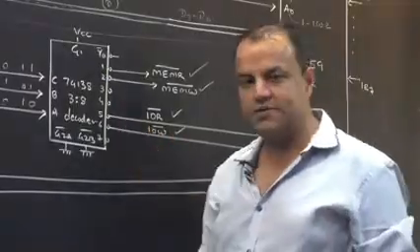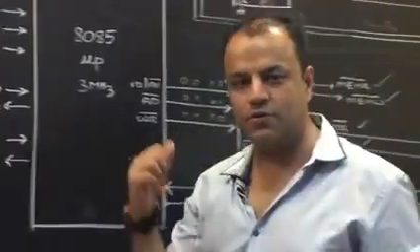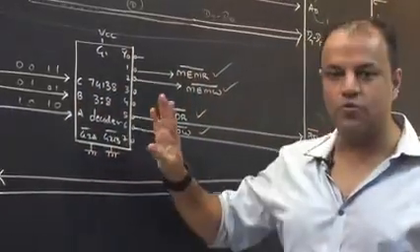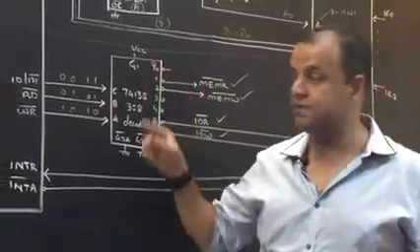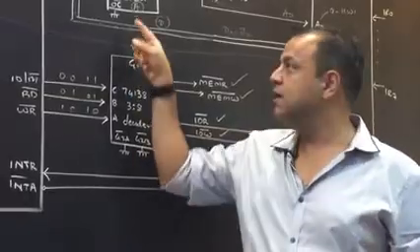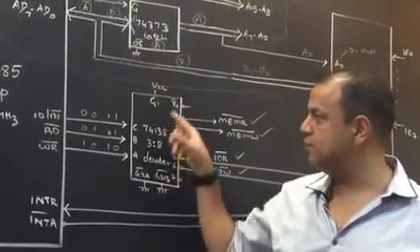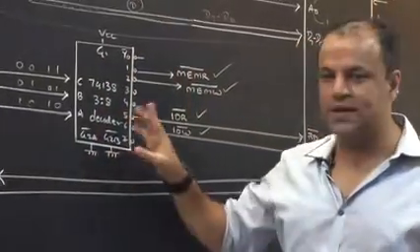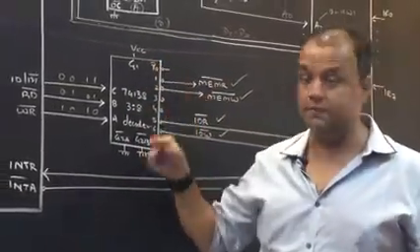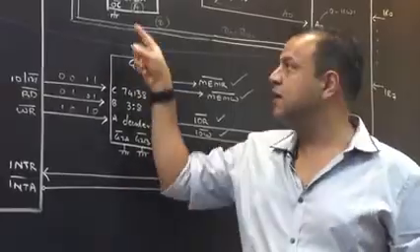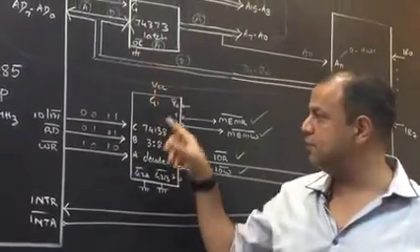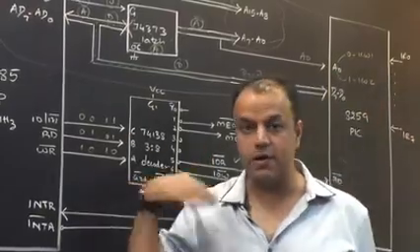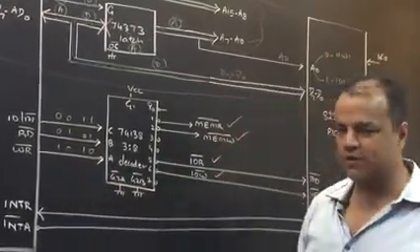You would be saying, why 3 enables? Don't worry. Decoders are not used only over there. Decoders are also used for address decoding. There'll be one more decoder coming in the circuit, and that decoder will produce that final signal that this whole thing is all about. At that time, we'll be using these signals extensively. In this decoder, we don't need them, but we can't just leave them. You still have to enable the decoder, like you enabled this OC bar by connecting it to ground. You still have to show VCC and ground, but they are not really required over here. They are required in the next decoder that we're going to make for address decoding.